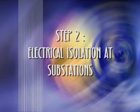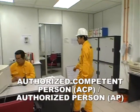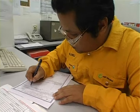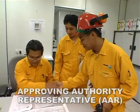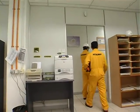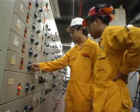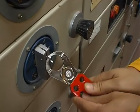Step 2. Electrical isolation at substations. In cases where electrical isolation is required, the authorized competent person, also known as ACP, or authorized person, also known as AP, together with the approving authority representative, also known as AAR, will go to the electrical breaker for the equipment at the substation. The ACP or AP must isolate the specific breaker, lock the breaker, and install a red electrical tag.